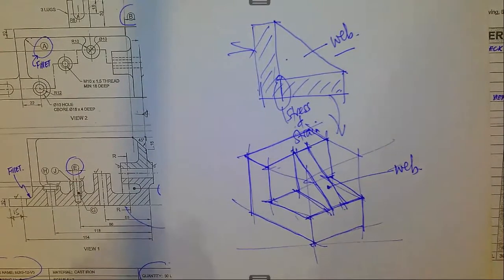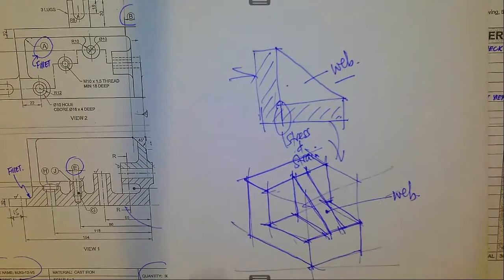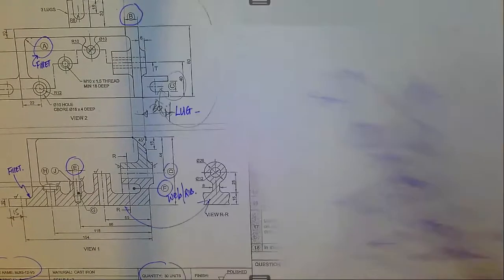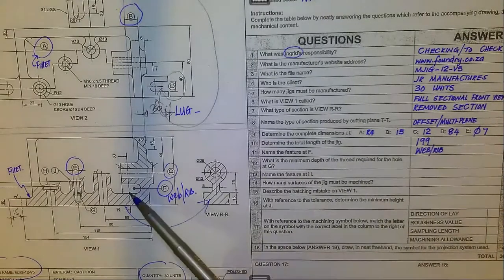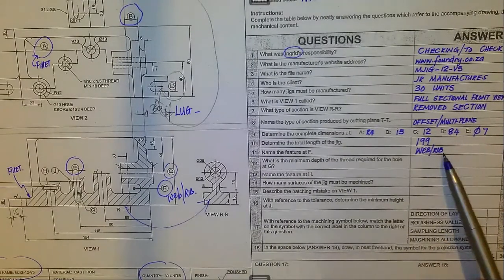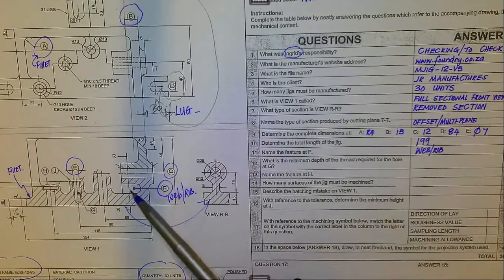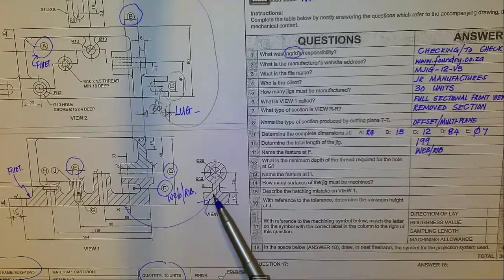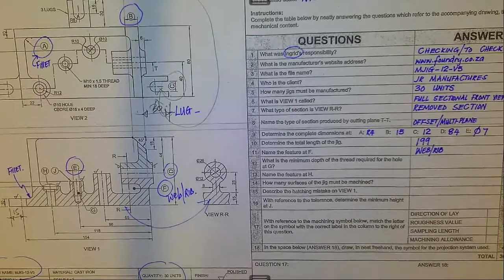You'll find that for some circular components, we may have something we refer to as a rib, okay? But the function and the purpose is basically the same. And in some cases, you'll find that these terms can be used interchangeably, one referring to the other or meaning the other. So that part is a web, it's a rib. But because here we are able to see the thickness of that web, when we cut it, we show it in section.